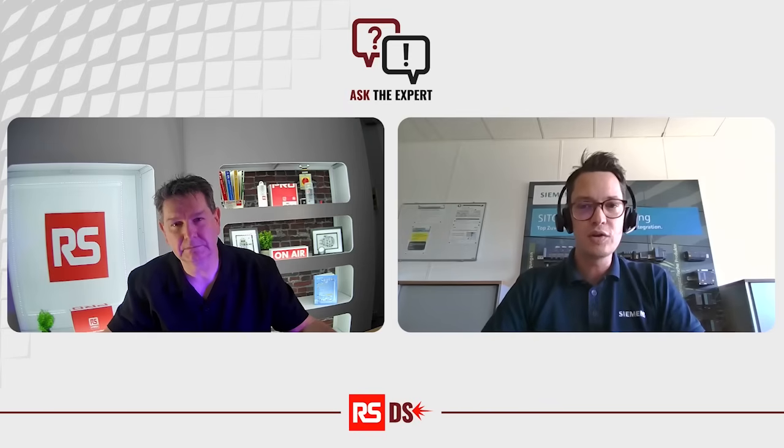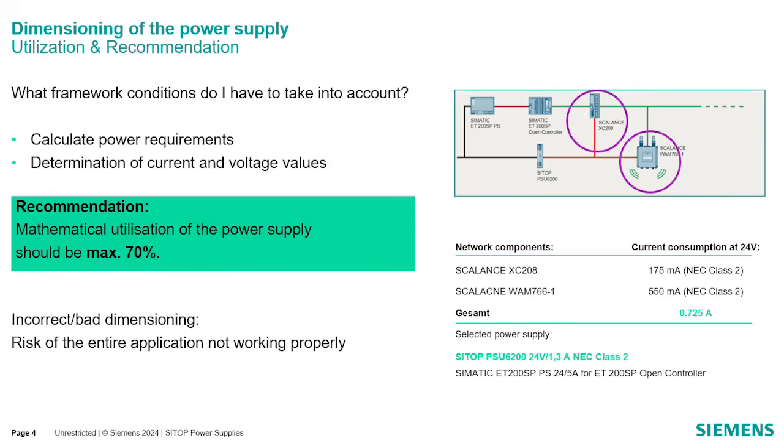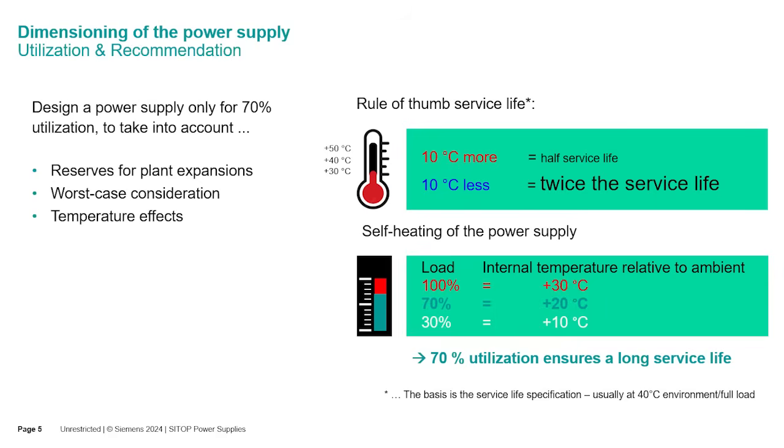If you want to optimize your application, there are several things you have to consider. Some are from the legal part and country-specific regulation, and also some from the technical point of view. I would suggest that you take a deeper look at your consumers and your loads. Then you take a deep dive into the technical data sheets from the consumers, and then you will see how the supply voltage should be. You can use it with 24 volt and also maybe with 48 volts and 5 or 10 volt.